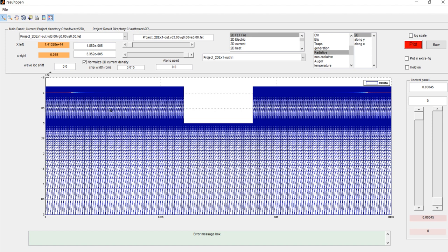If you say the current density is 20 amp per centimeter square, the actual current density could be 200, because all the current is crowded in this area. If this is like 1/10 of the area, the actual current density is like 2000. If it's 20, it's like 200. So the current is very crowded.